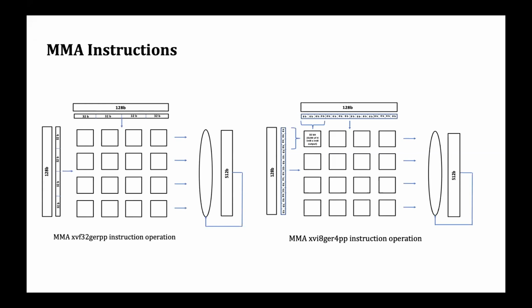We have not expanded the register file. That way, we are able to save power and we are able to save space. Real estate is very, very critical, given that we are running out of technology innovation. Once we move to 7 nanometer and 5 nanometer, post that, it's really tough to get more space in the chip. And obviously, power is also another factor we have to keep in mind. So with all that, with a 128-bit architecture, we are able to generate 512-bit results.